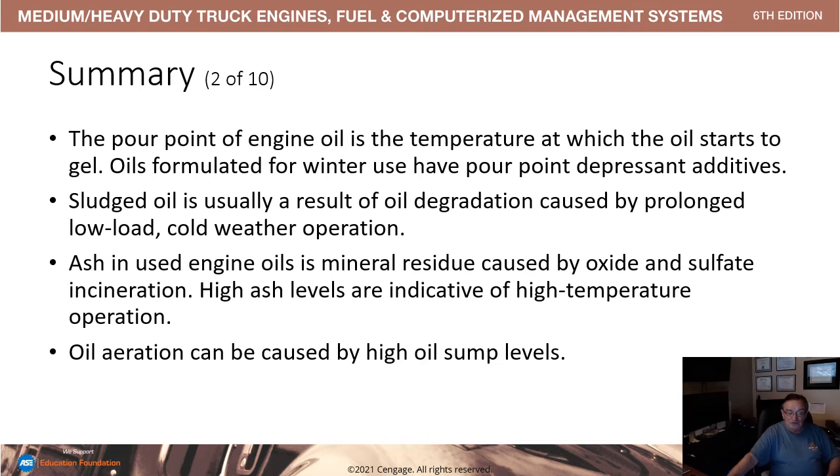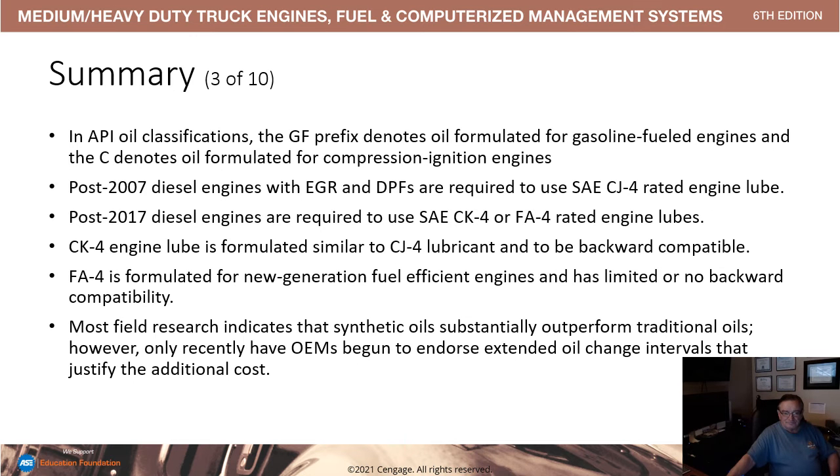Ash in engine oils is mineral residue from oxidized and sulfated incineration, basically byproducts of combustion. High ash levels are indicative of high temperature operation, and oil aeration is caused by high oil sump levels. If you have too much oil in the crankcase, you can have oil aeration.